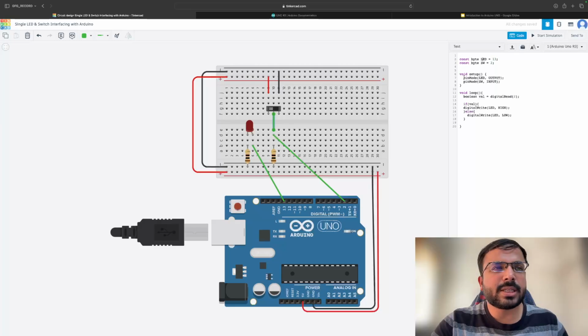One time setup initialization, I do it inside the setup function, connecting the LED, making the LED pin 13 an output, right? pinMode LED 13, right? Then taking digital pin 2 and configuring it as an input. Now I have taken a boolean variable, right? I read pin 2 because pin 2 is my condition of the switch.